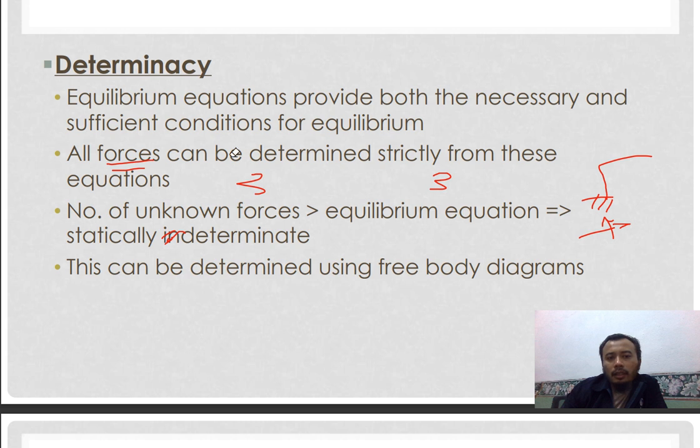But in the case when you find too many unknown forces, for example in this one, with a pin here, you have at least 5 unknown forces, but you still have 3 equilibrium equations. So the structure is statically indeterminate. You cannot solve the structure and the unknown forces using only these equations; you need statically indeterminate analysis.